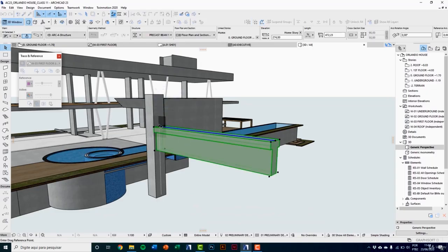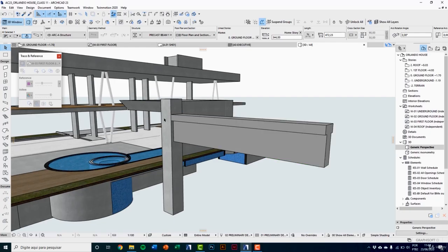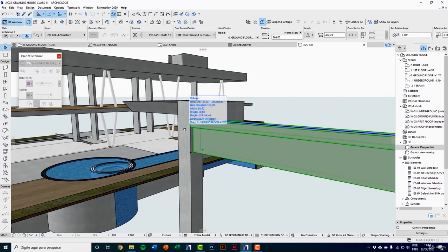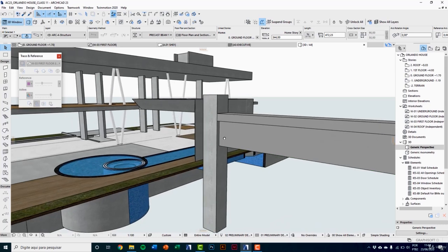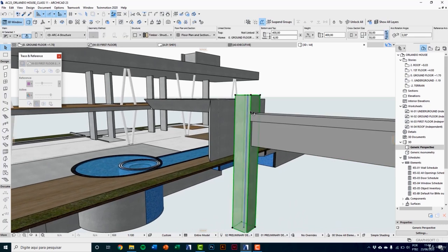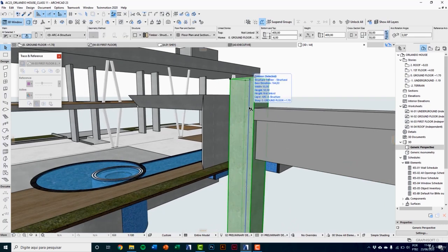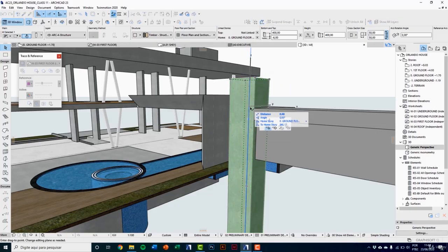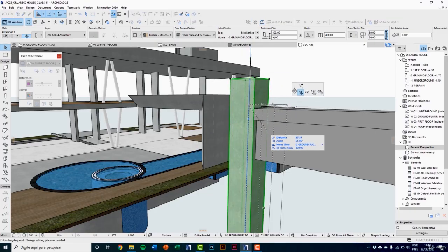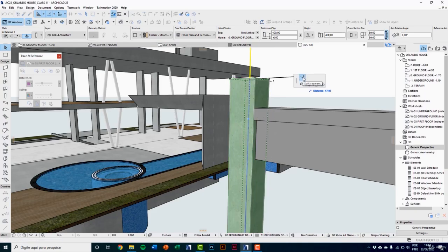and on 3D I can make an adjustment. And now I'm gonna show how to do variable sections even on 3D window. Select the column and you see this blue line on axis. Clicking on it, you can see the floating palette. We have this option split segment. And now click at the bottom part of the bin,